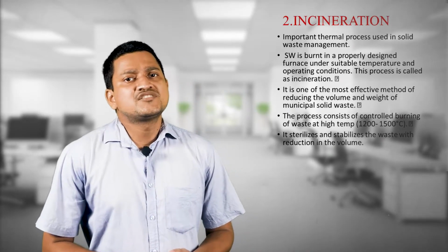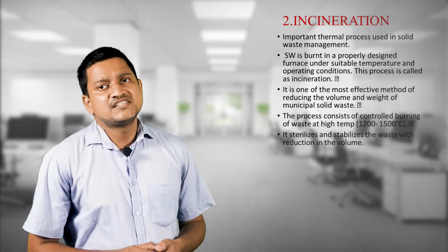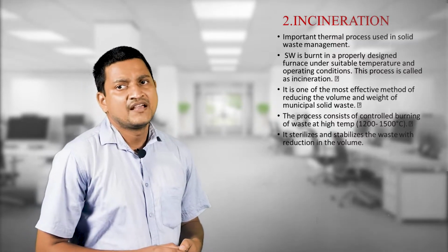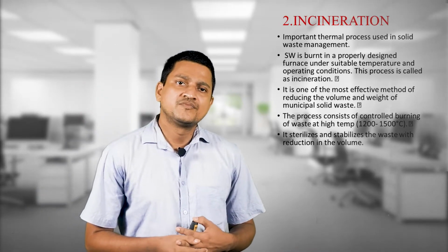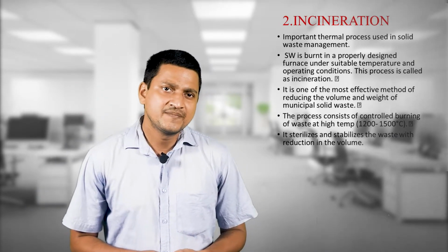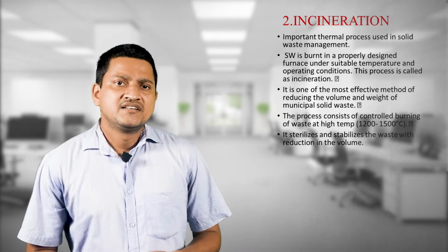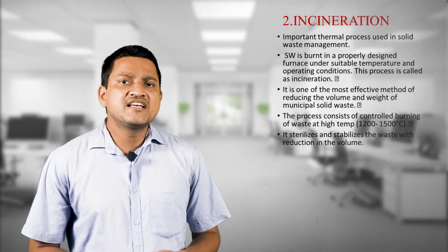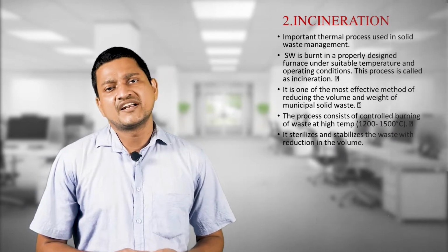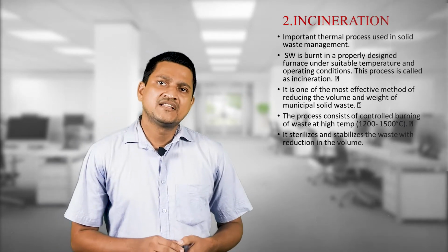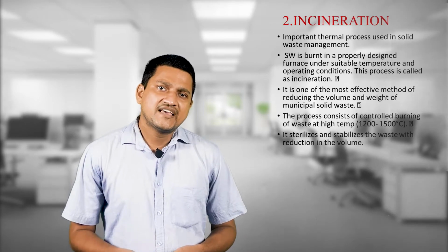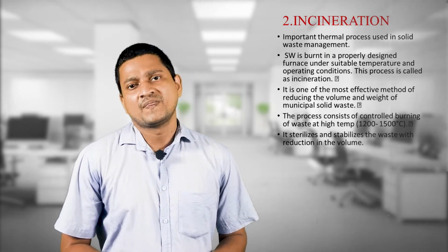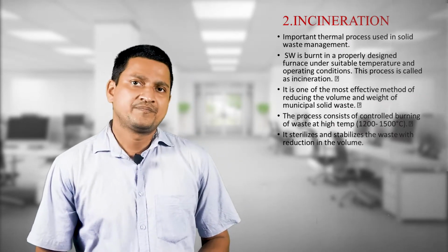The process consists of controlled burning of waste at high temperature, that is around 1200 to 1500 degrees Celsius, to sterilize and stabilize the waste with reduction in volume. That is the advantage of incineration.